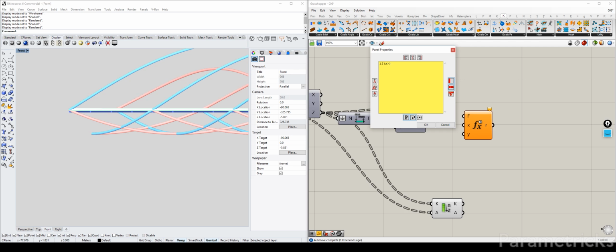bigger than 1, or let's give our script a little bit of leeway, 0.99. That's very close to the 1, and we can be sure that with whatever tolerances are built into Rhino, 0.99 is going to be within that tolerance. So we can be sure that the top points will be culled. And we can say if you are bigger than 0.99, I don't want you. Else, true, I want you to stay.